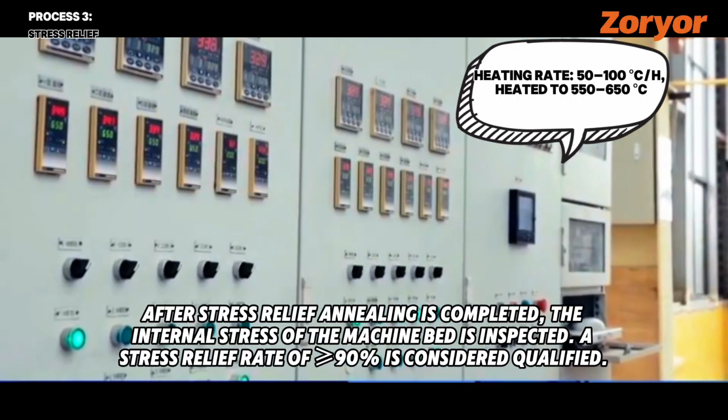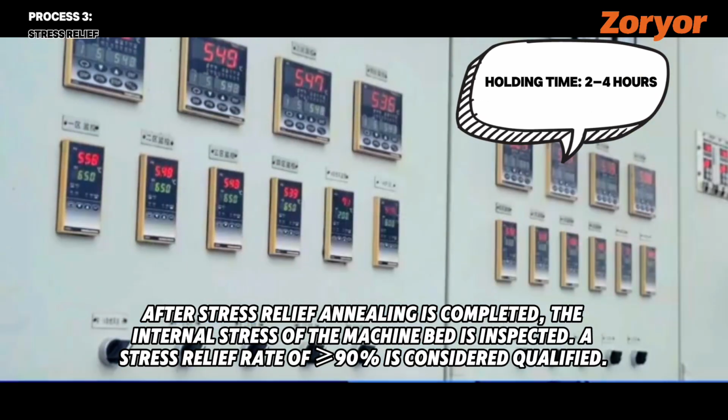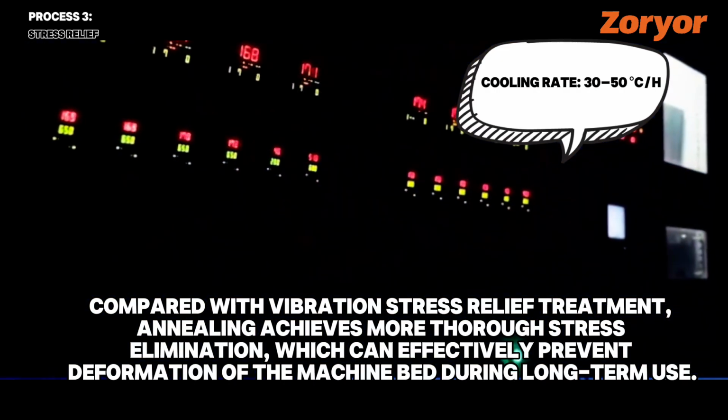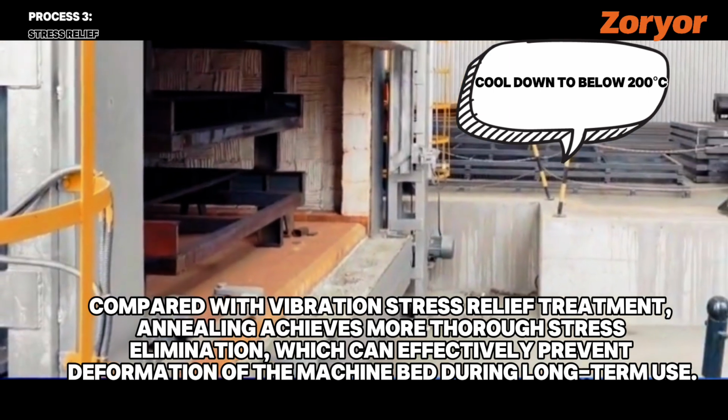After stress relief annealing is completed, the internal stress of the machine bed is inspected. A stress relief rate of 90 is considered qualified. Compared with vibration stress relief treatment, annealing achieves more thorough stress elimination, which can effectively prevent deformation of the machine bed during long-term use.